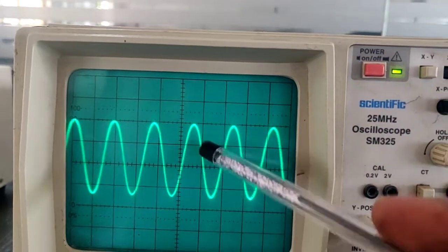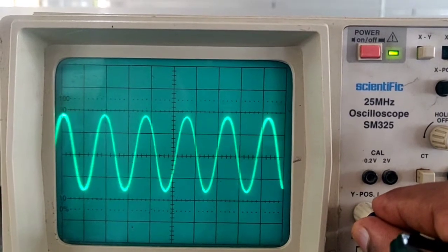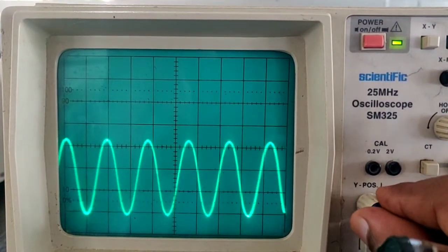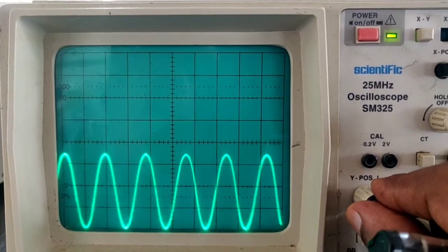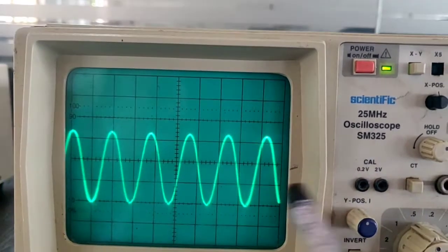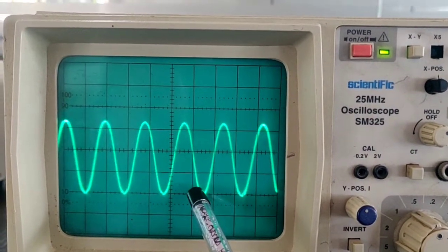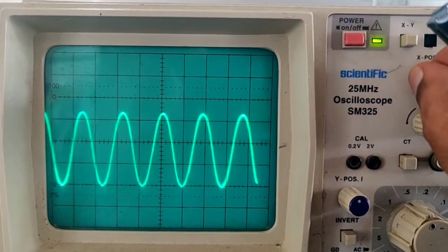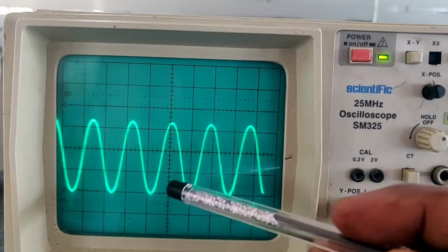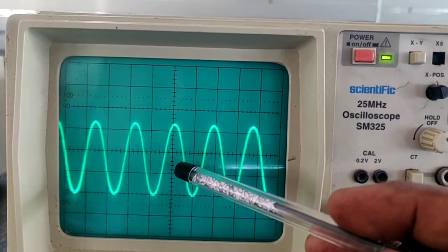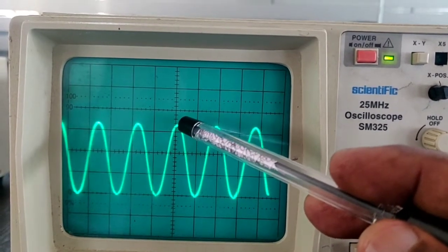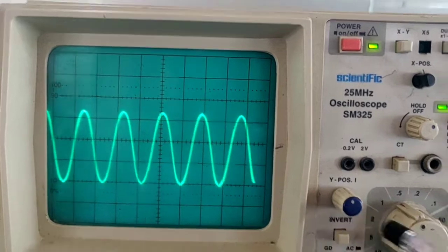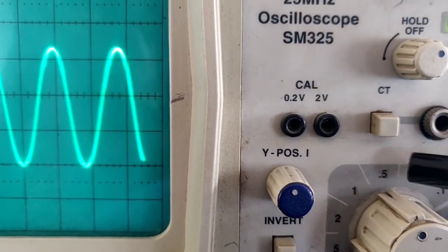So now let us measure the amplitude. I can position this signal by using the first channel up and down control on any reference line. You can position this here or here or even at the bottom. The option is left to you. So I am going to select this position. For me, for measuring the amplitude, this will be the reference line. Now slightly I will move this to this position. Okay, it is now exactly on the y-axis. Now I am going to measure the number of divisions here. 1, 2, 3, 3.5, 4. Okay, each subdivision is 0.2, so it is 3.4. So 3.4 into, what is the control reading here? 0.5 volts.